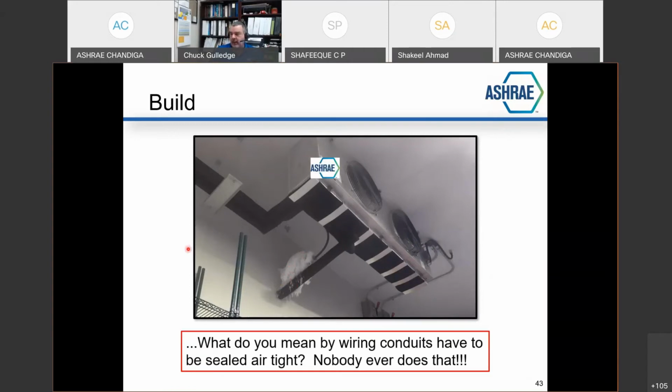inside a freezer. Why is that doing that? Vapor pressure inside a freezer is so much lower than vapor pressure outside in a hot, humid climate. Moisture is going to push its way into this inside environment here. And just a simple unsealed electrical conduit that communicates outside of this box, there's enough moisture in there that you start making an ice dam.